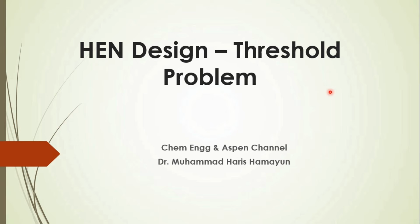Our topic today is heat exchanger network design related to the threshold problem. This is not just another Aspen tutorial. In this video, we will combine pinch analysis concepts, threshold problem logic, Aspen Energy Analyzer simulation, and the use of an Excel sheet into one complete workflow. This is exactly how heat integration is done in real process design projects.